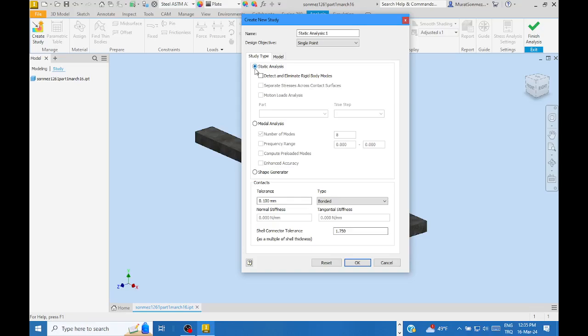But if your purpose is to determine resonance frequencies, then consider the frequency of the actuator, whether an electrical motor or the turbine of an aircraft. There is a dynamic load exerted in most cases by a motor, electrical motor, or combustion engine.